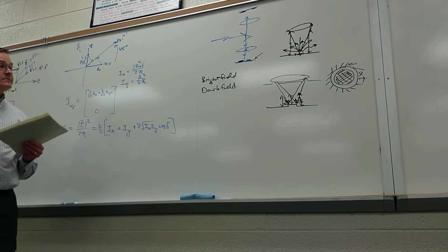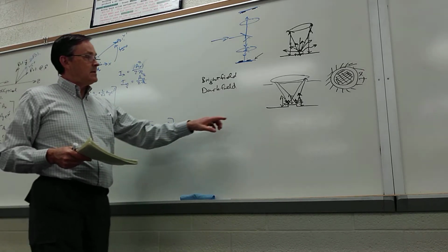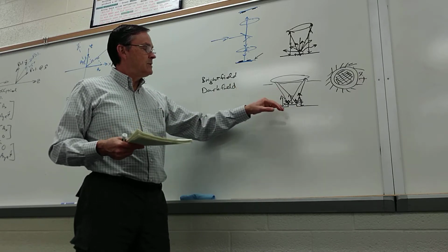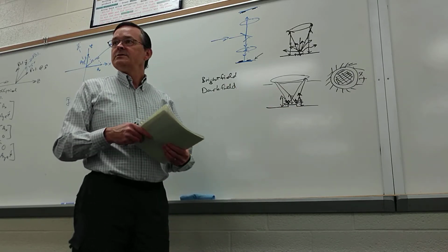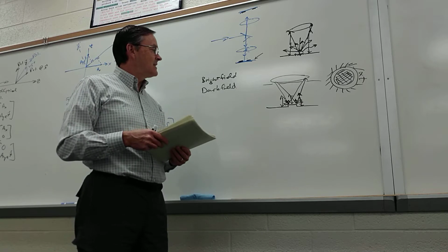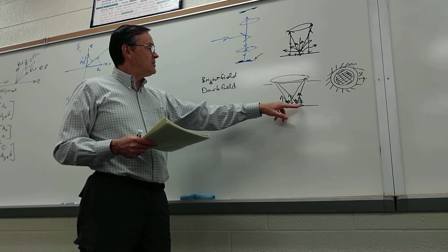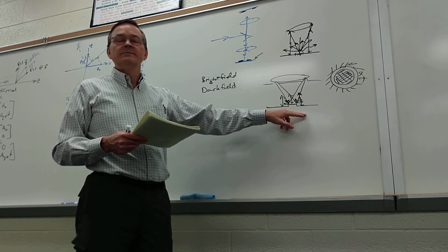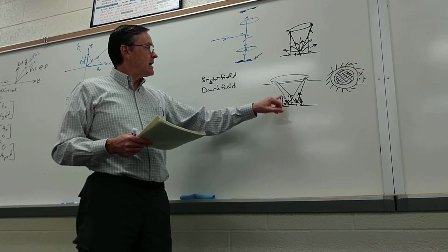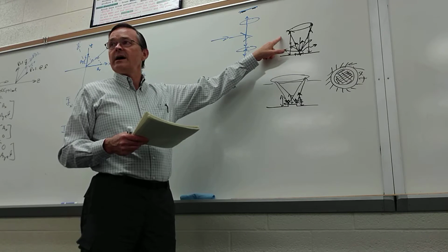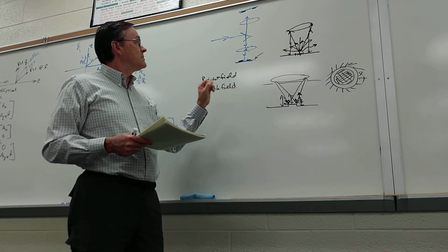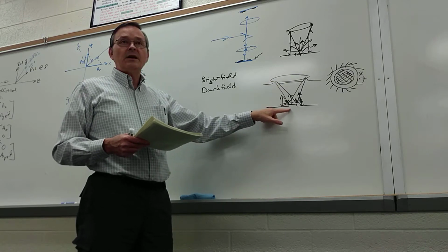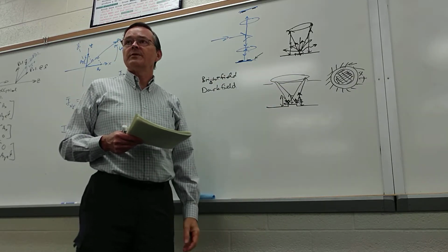Or let's say this is silicon, and you've just got an etch here, say a 200 nanometer deep etch. You stick that in the microscope, and everything's going to look kind of the same because the reflectance is the same everywhere, except on the edge, maybe you'll scatter a little bit of light outside the entrance aperture. But if you flip your microscope into dark field mode, suddenly those edges just are bright. You'll see them very clearly.